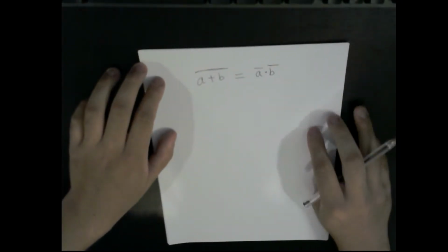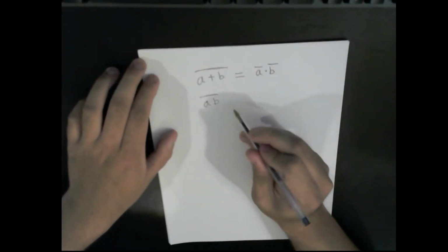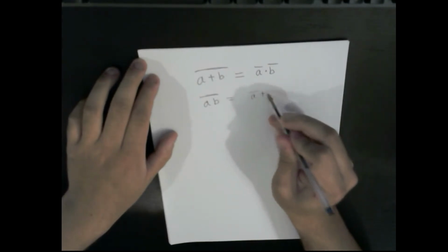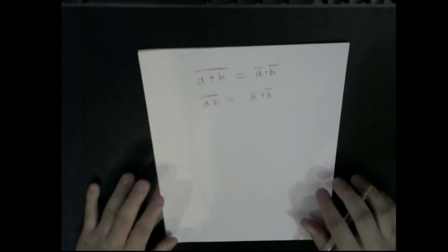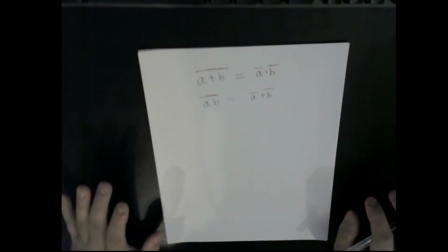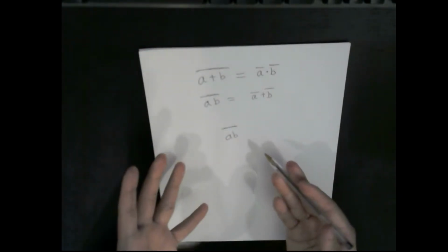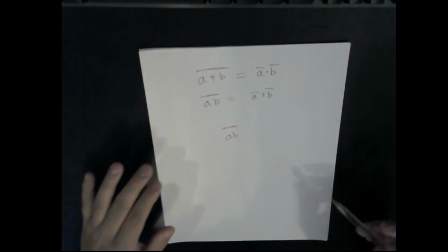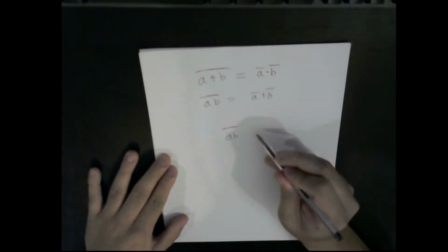And we can do something else like A, B, or like this. These are equivalent expressions. So there's a nice mnemonic I like to remember with DeMorgan's Law, and it's called break the line and change the sign. So let's say I have this AND equation right here, and I want to convert this to using ORs. How can I do that? Well, I want to apply DeMorgan's Law. And what DeMorgan's Law says is I can break this line on top and change the sign. So if I have a bar on top of these two elements, I can distribute this bar.